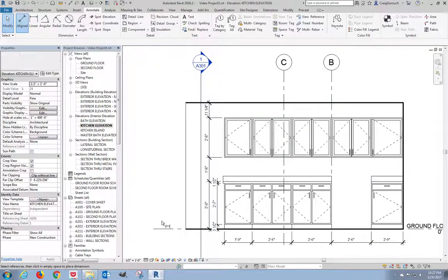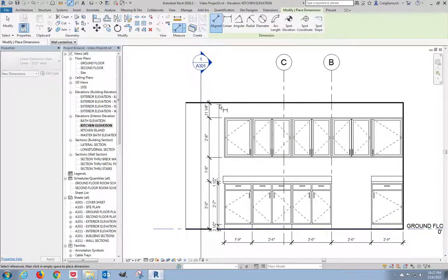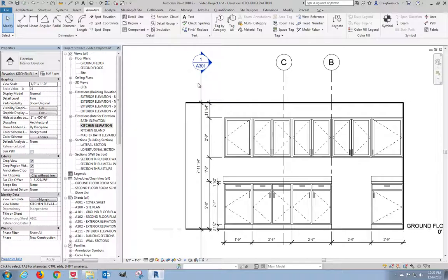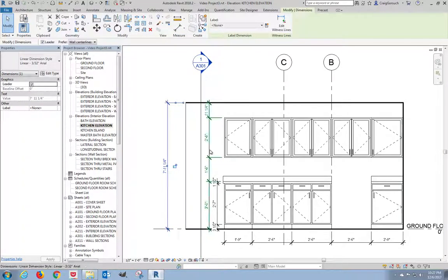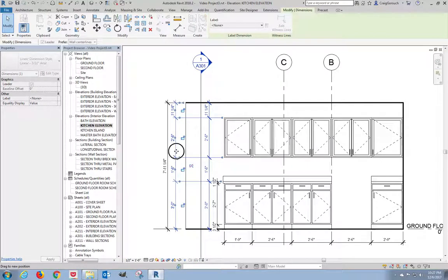And now let's add, to make it match all the other dimensions, one more dimension string, just like that. Now unfortunately, this building section is kind of in the way of that information. So I'm going to pull this out a little bit. It's going to take up a little more space through here than I really want it to.